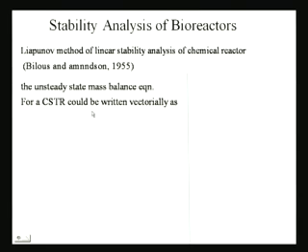from 1955. So, what we have to do is write the CSTR equation in an unsteady state form now. We looked at the steady state, and we wrote the unsteady state equations before, but we did not solve them at that point of time. Neither are we going to solve the unsteady state equation now, but we are going to analyze the stability of the steady state using the unsteady state form. Now, I want to give you a generalized way of looking at it, and therefore I use a vectorial form of it.